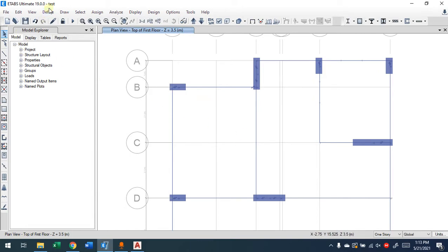Now let's say you have the slab. I'm not going for the different types of slab like waffle. Those you can manage by yourself, or you can do the secondary beams, then draw the slab as normal. Both of them are possible. Now in drawing slab, we have 3 options there. There is draw quick floor, there is draw rectangular floor, and draw floor panel. So this is kind of for irregular shapes. I can do it. This is only rectangular, this is quick. Now quick, you realize that it only draws between the grid lines.